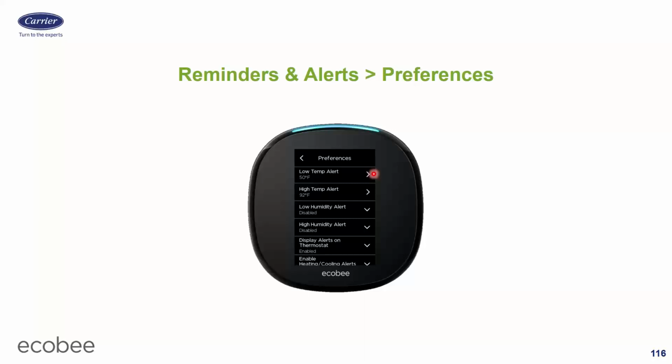I do that because if I set them right at each other, then if any little blip happens and I happen to get a 1/10 of a degree below it on accident, I'm going to get this nuisance alarm. Once it's 5 degrees below, okay, this is a real problem. My heat obviously is not working, or my kid propped the door open, one of the two. Same thing on the high temp side. If you're going to set it to be 80 degrees when you're away, alarm it at 85.